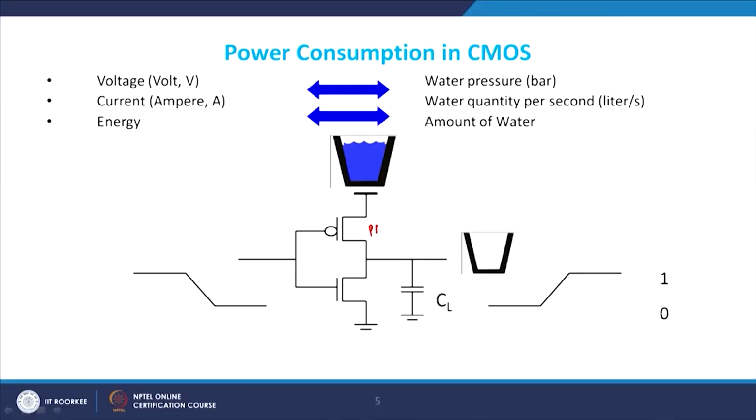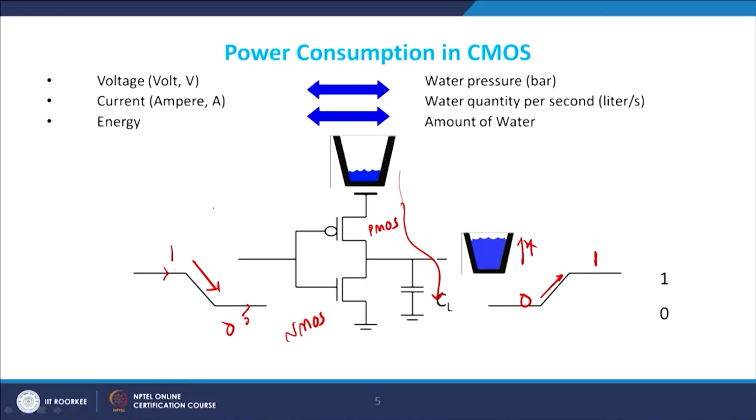Now, let me see what is the power consumption. Let us suppose that this is a MOS device, this is PMOS, and this is your NMOS here, right, and your input goes from 1 to 0. So, when it was initially 1, this was on, and therefore CL had discharged, and now you are giving a 1 to 0 transition. Once you give a 1 to 0 transition, then what you see very interestingly is that the voltage falls across this path and charges my capacitor CL, and therefore the voltage here rises, and you have a 0 to 1 transition taking place here, right. So, I have a 1 to 0 transition at the input and it goes from 0 to 1 at the output, fine, and this gives you an idea about how fast or slow your design is, right. So, when you are doing it, you are actually drawing power or consuming power from the VDD rail, right, because charge has been drawn from the VDD rail, and you are able to therefore have this power available to you.